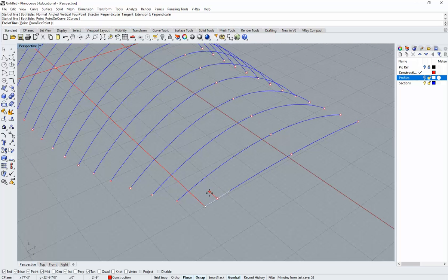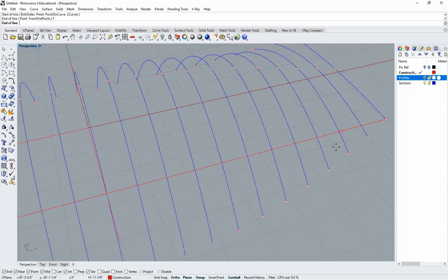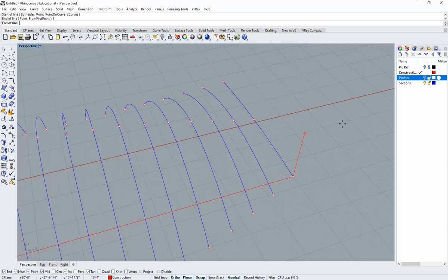And now make sure you're remembering to hold off for a second, click first point up in the top, or just type in F, that will also work. So if you type in F or click this button, it's going to force the line to begin at the point you just selected, which was the end. The end of a line now is going to ask you to select somewhere in space. Now here's where if you hold shift and you're not snapping to anything else, it will draw it perpendicular up in the Z direction.